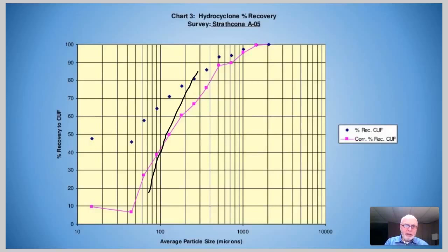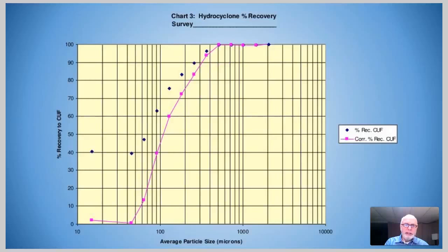Another thing that you'll note about the difference in the performance of these standard versus newer cyclones is the very coarse particle range. Up here, you'll see that we're losing some very coarse particles to the cyclone overflow where we definitely don't want them. Whereas with the newer, higher efficiency, high performance cyclones, it's actually collecting all those particles, 100% of them, to underflow. So this is the third factor in obtaining high CSE, and that is the use of well-designed, modern, high-efficiency cyclones.